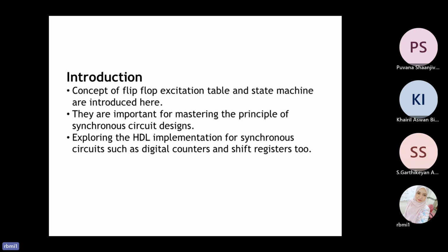Synchronous circuits are electronic circuits that are designed to operate in synchronization with a clock signal. In a synchronous circuit, all the circuit elements such as flip-flops, registers and logic gates are designed to operate only when the clock signal is in active mode.